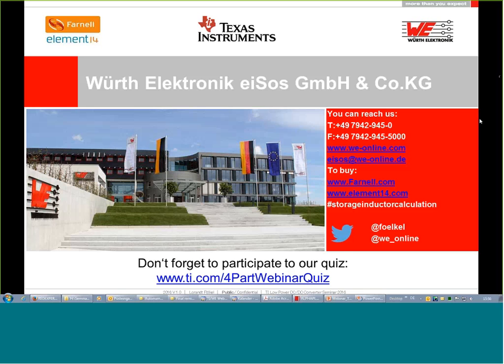That's the reason why a boost has a higher ripple and higher problems on the output: you increase the current and the inductance value, additionally charging the inductance with a high current, and then you want to transfer this current into the voltage, and you automatically have higher EMI noise on the boost.